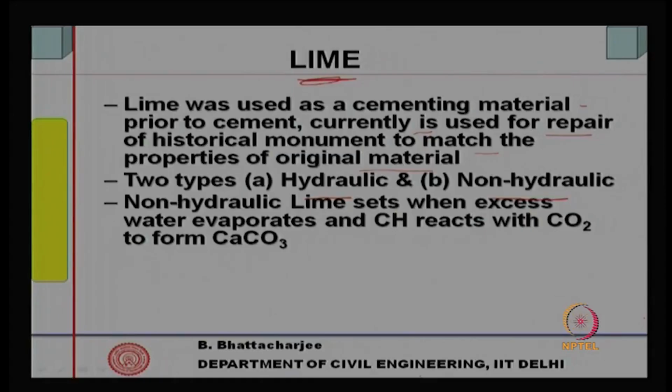Non-hydraulic lime sets when excess water evaporates and calcium hydroxide reacts with carbon dioxide from the atmosphere to form calcium carbonate, therefore, the setting occurs.